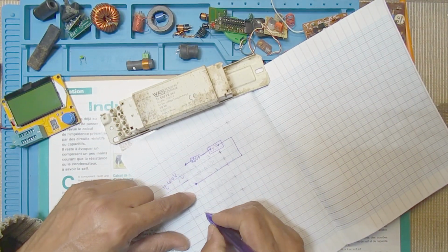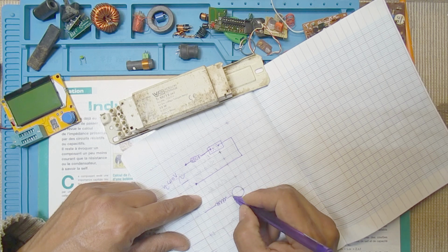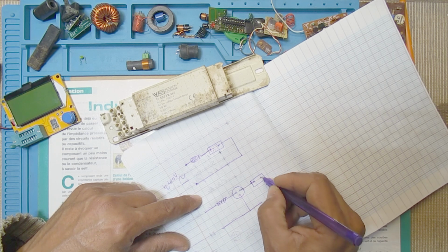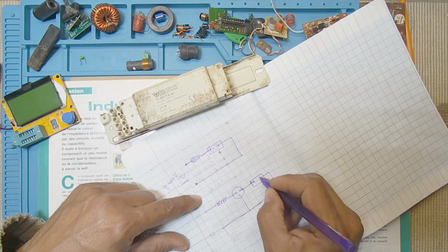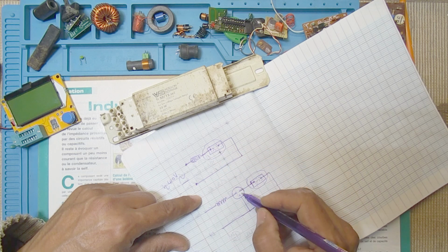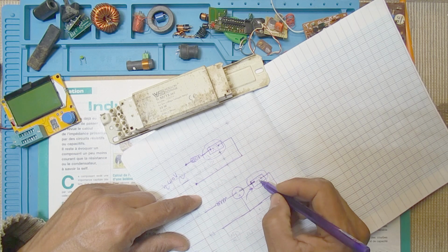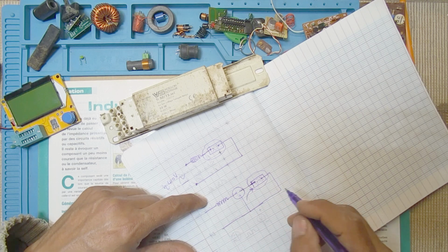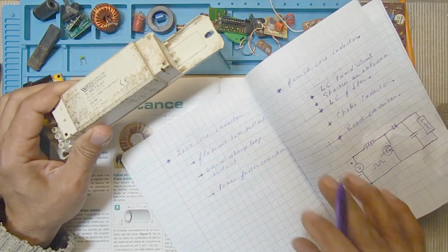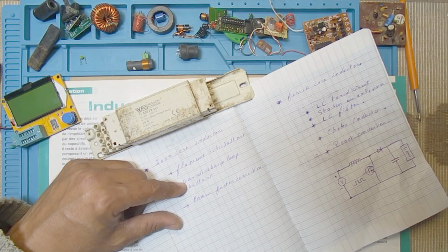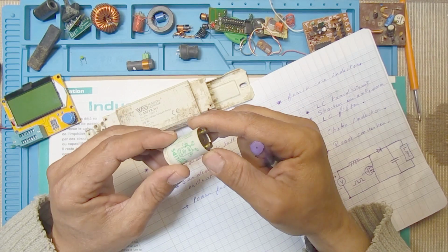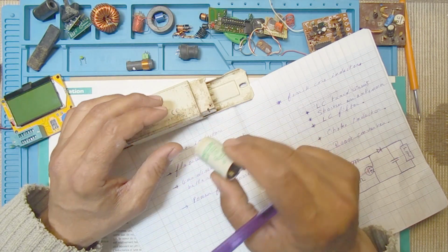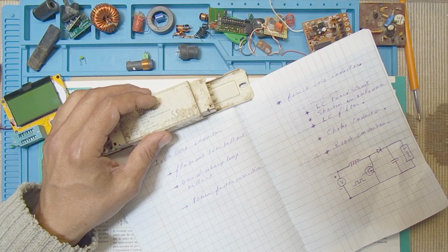Of course, the circuit needs a generator. This generator makes a high voltage strike to ionize the discharge gas here for the lamp, for the bulb. This generator will make a high voltage spike here, and then the ballast will regulate the current. For the fluorescent tube, we have the starter that will cut the circuit, so the ballast will make a high voltage to the fluorescent tube, and then it will regulate the current.